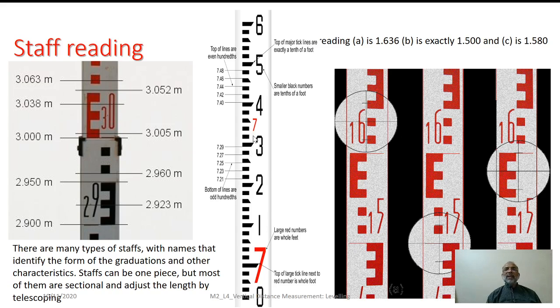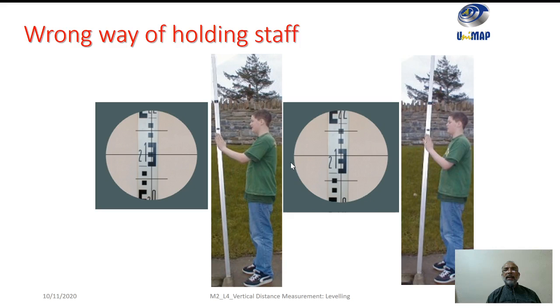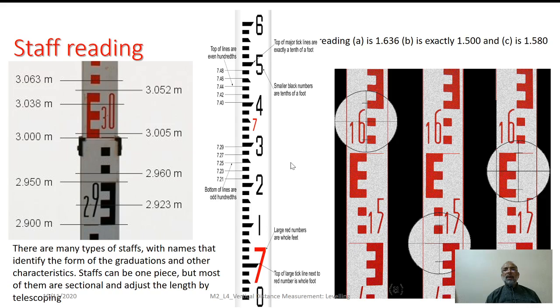So, as we look through the telescope, the lowermost portion is to be read as 0.00, whereas the uppermost portion of that particular division will be read as 0.005. Firstly, we have to take a reading of the leftward figure, which covers the height in meter.